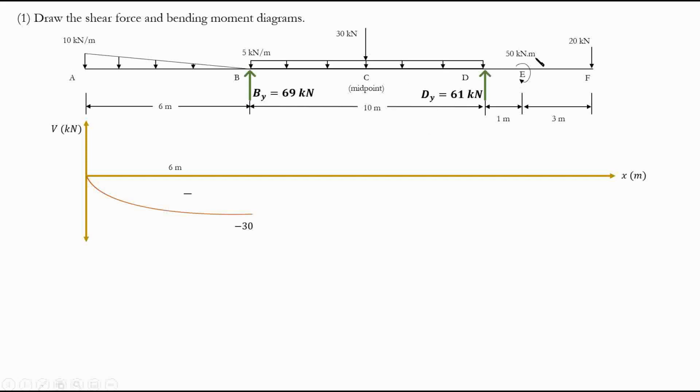And then here we have nothing, right? So we have no load. Load does not exist in terms of the distributed load, right? So when distributed load does not exist here, it means that for the shear force diagram, you're going to deal with a 0 degree curve, right? Or a constant line. And for the moment diagram, again, upgraded, a first degree curve, right? For a moment it will be a line, right? Simple as that. So if you remember these, that will be enough for our basically drawing our shear force and bending moment diagrams.